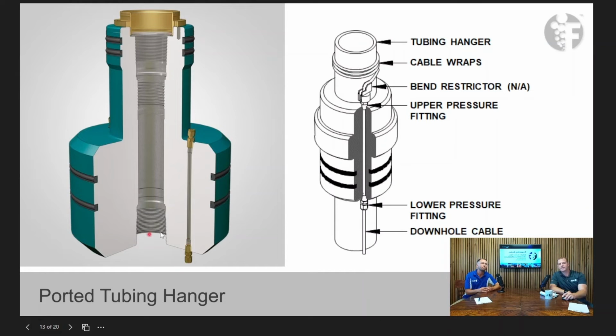That makes sense. So different than your production tubing, you're actually passing that cap tubing through the hanger. Right. You're not just cutting it and hanging it off the bottom, just like you would with your production tubing. No, you're not doing that. So the cap tubing's continuously pushed through and then comes out usually about a foot, 2 feet out of the wellhead. Okay, that's good to know. So if you're doing 1/4, get the wellhead hanger company to cut a 3/8. Yep. Could you do 1/2? Is that okay? Yeah, you can. Yeah, the bigger the better, right? So if you standardize on a 1/2 inch borehole in your hanger, then you should cover everything.